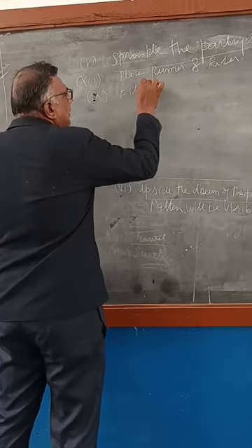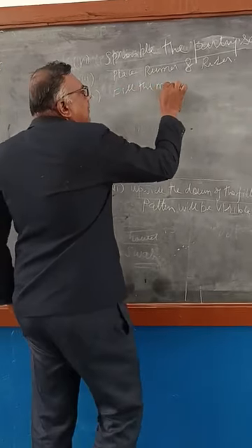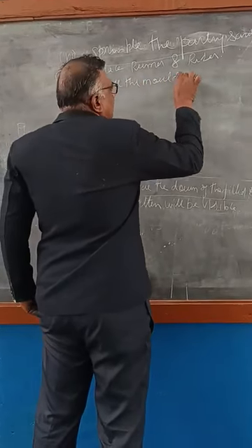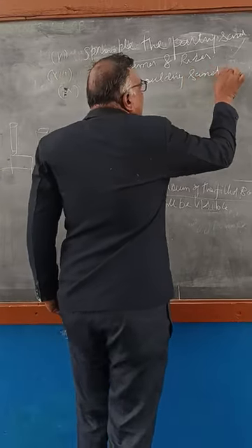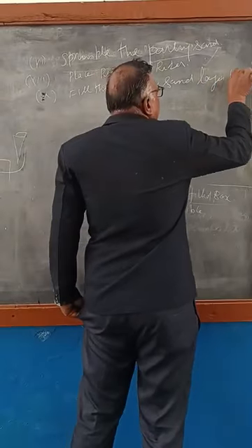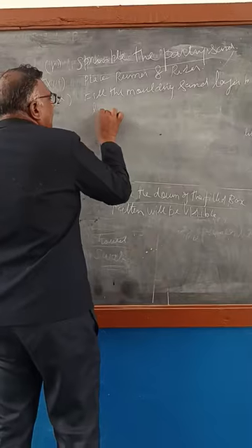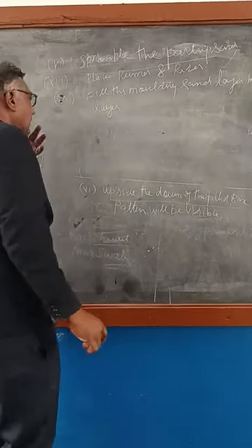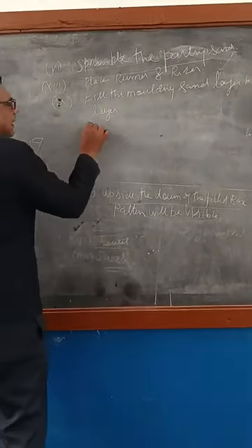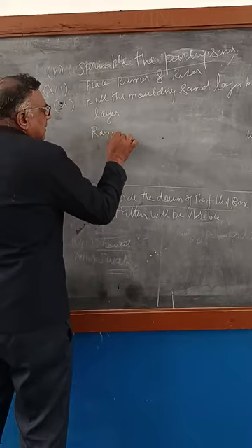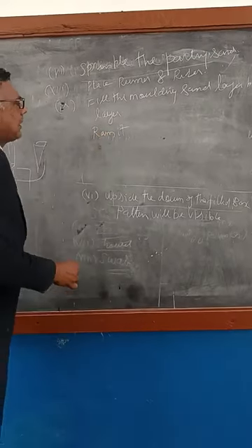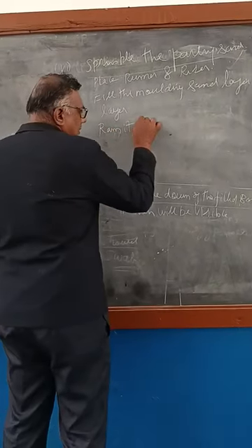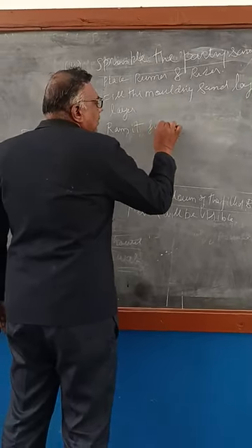Fill the molding sand layer by layer, move inside layer by layer and ram it, ram it to fill the box.